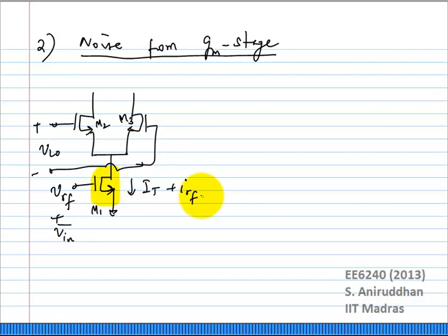What happens is the signal, this IT plus IRF, gets multiplied by a sum of sinusoids. So you have a sin omega LOT term, you have a sin 3 omega LOT term, a sin 5 omega LOT term, and so on. Obviously the amplitudes of these are also reducing because it's a square wave. Correct? If you had a noise VIN at the input, whatever happened to VRF, the same thing would happen to VIN also. Correct? So let us analyze it that way.